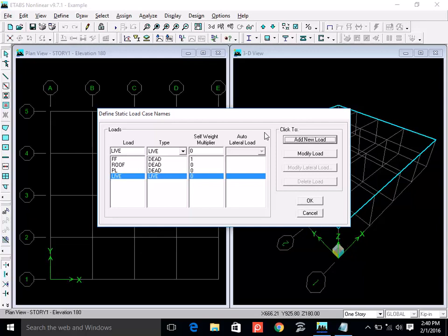So you can use those values, but all of them are actually live loads. The generic is live, so you don't have to define multiple live loads. And it includes furniture, not just human beings. For example, if the load for the classroom is a specific number, say 60 pounds per square foot, it includes human beings and furniture and fixtures, whatever it is.